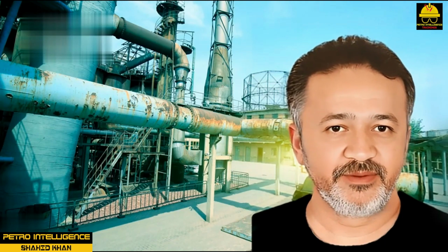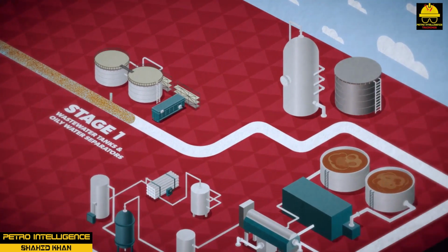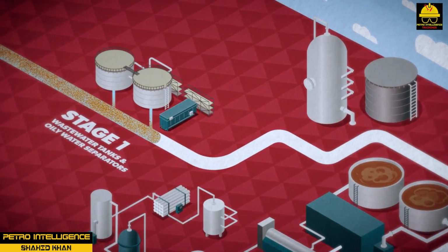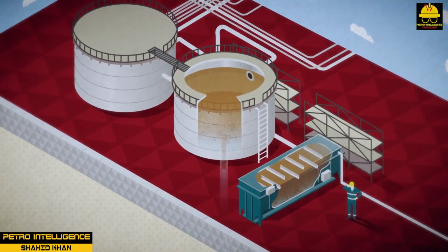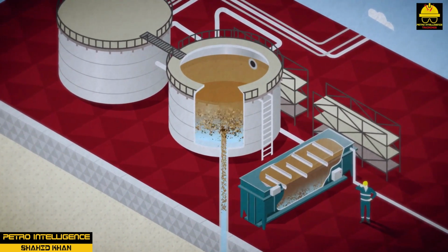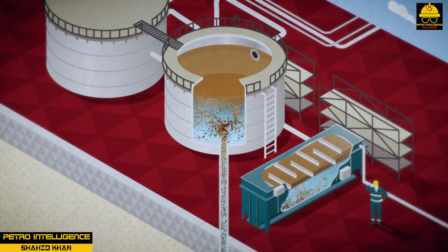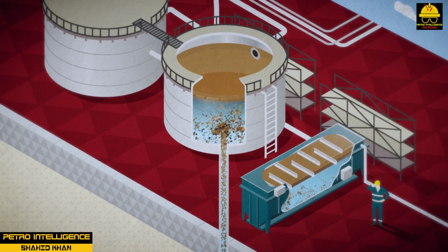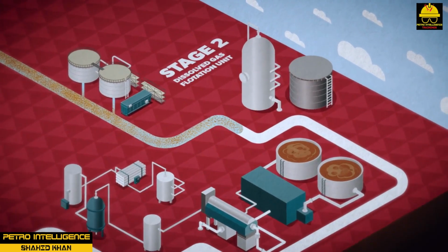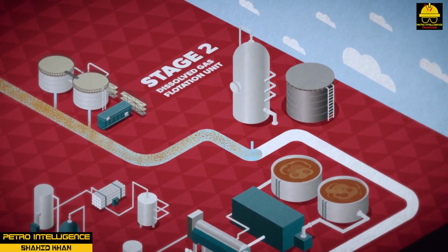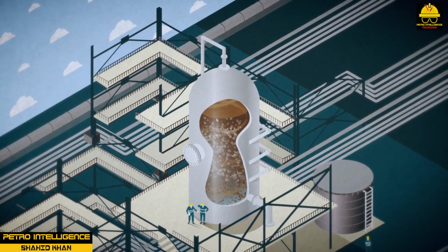Industrial sewer system. A plant sewer system collects all drains, water and process fluids from the process units. All water is collected in a series of ditches and routed to the plant waste treatment area. Units that have hydrocarbons that will remain in the liquid phase at ambient temperatures have an American Petroleum Institute (API) separator, which separates the oil phase from the water phase before routing the water to the plant sewer system. Removed oil is rerun or used for fuel.